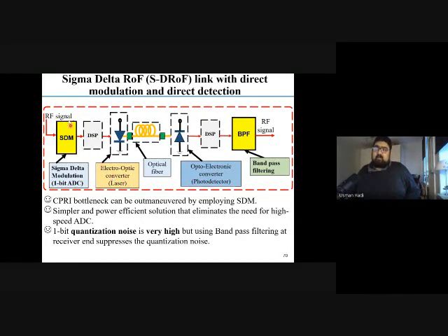That is the concept of using Sigma Delta modulation, that you have a 1 bit ADC here. But the problem is that, if you remember your digital signal processing slides from undergraduate level, we have that staircase which shows that the lower the resolution, the higher is the quantization noise. So if you have a 1 bit ADC, the quantization noise or the noise floor will be very high.